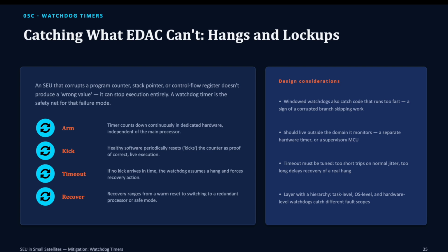When we have the error detection and control level, there are some things that this kind of technique cannot catch. When an SEU corrupts a program counter or a control flow register, it doesn't produce a wrong value. It can just stop the execution. So a watchdog timer is the safety net for this failure mode.